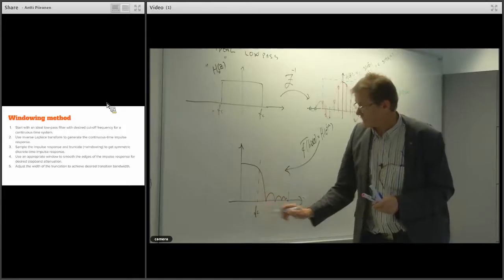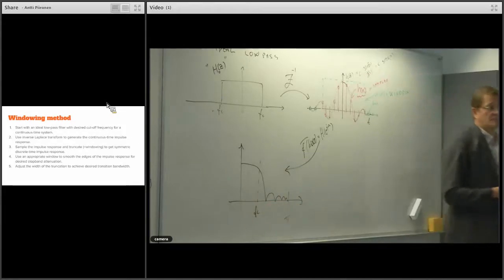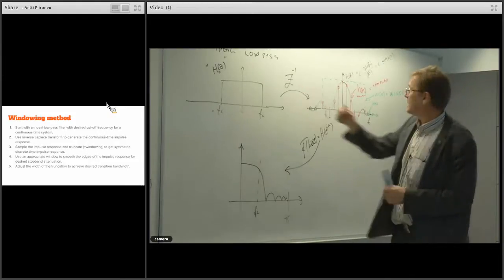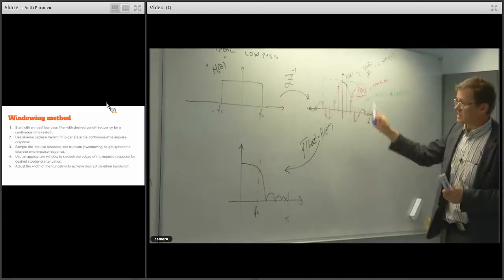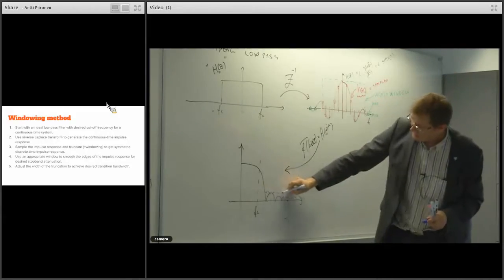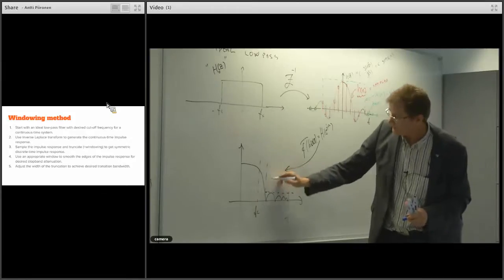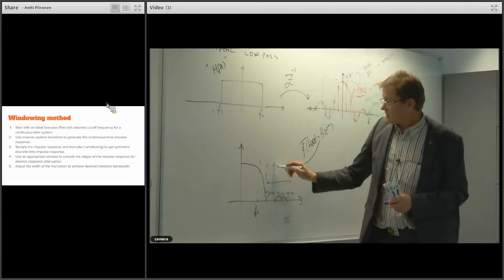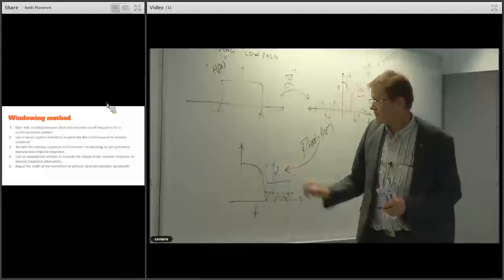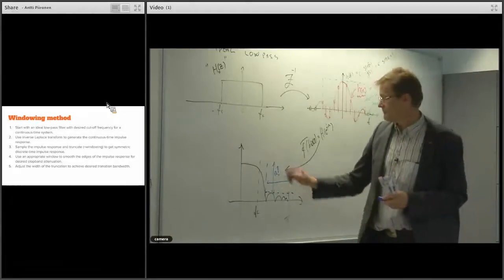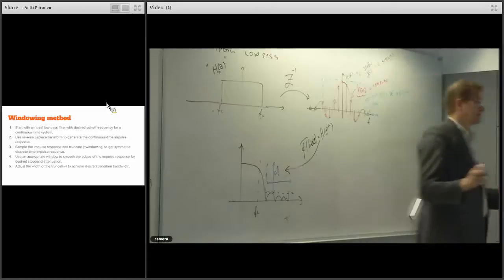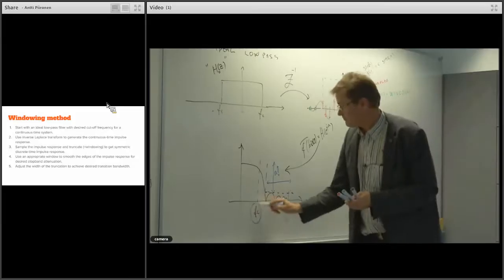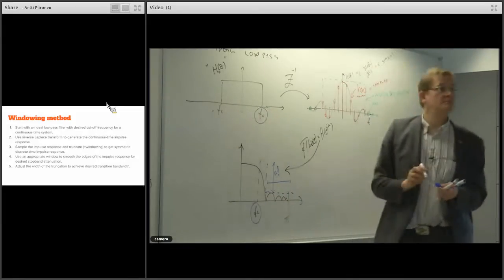With a given cutoff frequency, we get some non-ideal parts there too. This was ideal, but in reality, when we were doing truncation, we also generated realistic stop band properties here: stop band width and also the attenuation. But the passband is okay. This simple method will give a correct passband for the system.